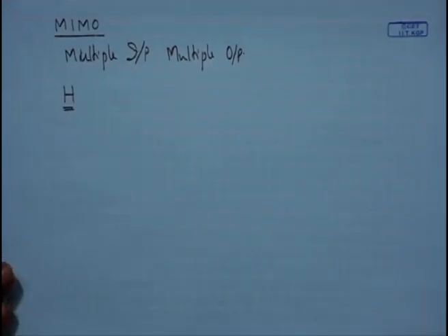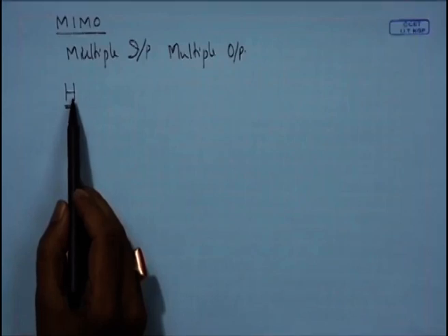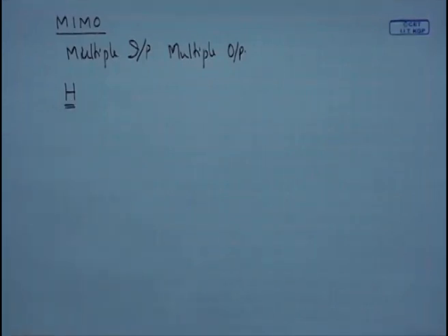So the way we have come across is we have started from time, frequency, now to space, and then we have taken Fourier transform of the channel in the delay axis, in the time axis, inverse Fourier transform from the Doppler axis, then there was the space, this angle. There are so many things that are going on. You would often get confused with the number of variables that are required. So in many cases, when you are not studying the space dimension, that means when you are not studying the multiple antenna dimension, usually the habit or the technique is to represent capital H as the Fourier transform of small h, and that means we are talking about the transfer function of the channel.